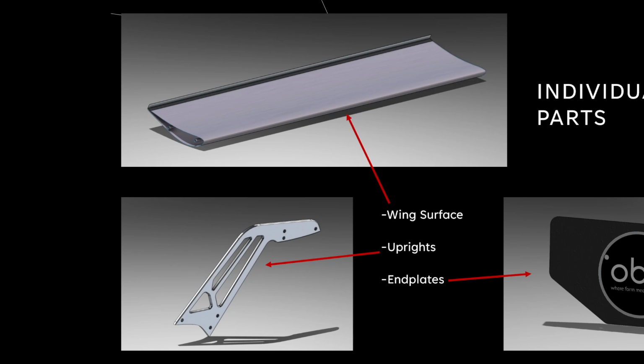And then on the bottom left, you have the wing uprights. I initially designed these to just be cut out of sheet metal, just flat, I believe 1/4 inch, 7075 aluminum. But now that I've gotten deeper into the design and I've added chamfers and done a couple of things with it that I think add to the overall aesthetic design, because I really want the aesthetics to match the performance, I think I might get them machined out. It'll be more expensive, but it's baller. So, you know, you give some, you take some.